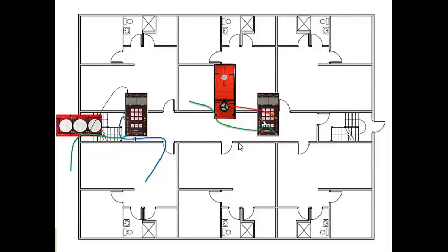on channel B. So what we're going to do, like when we're doing a duct leakage outside test, we're going to want to get this fan at the same pressure as the rest of the building. So the building's at 50, we want this unit at the same pressure, so we're going to be shooting for 0 pressure in that unit.